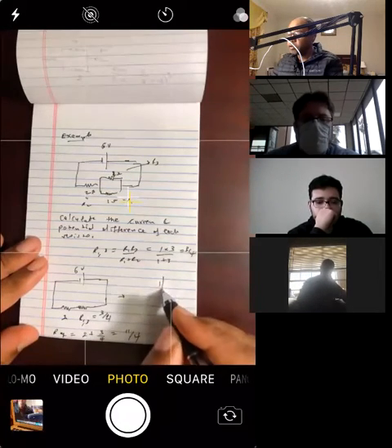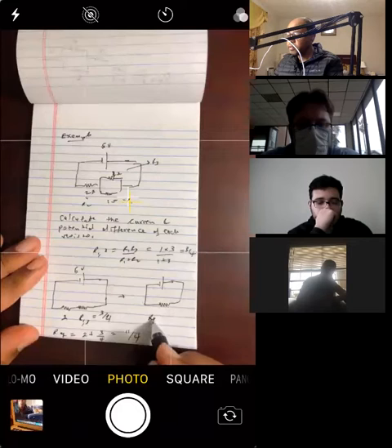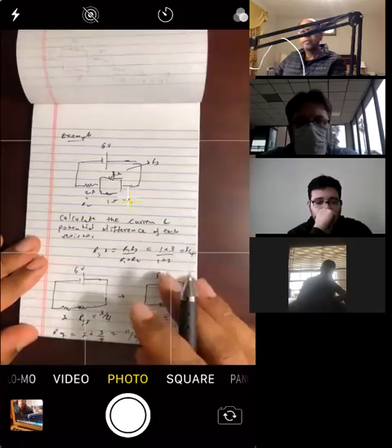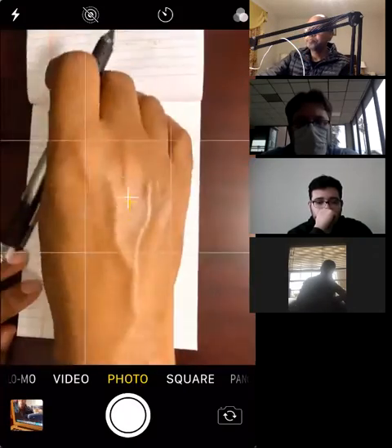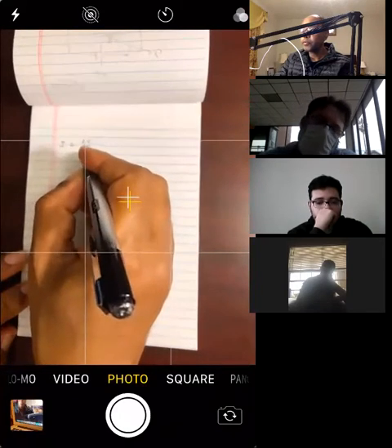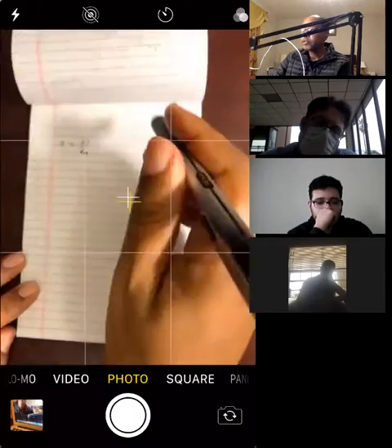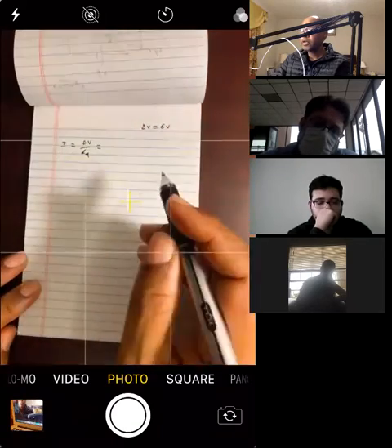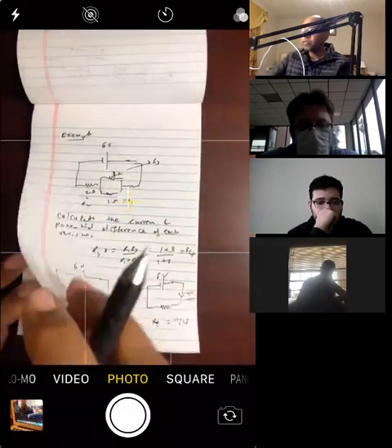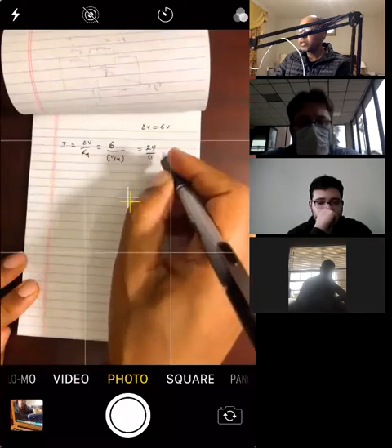So this simplifies to the following circuit. So you have a single resistor, which is the R equivalent, 11 over 4. Okay, you got 6 volts over here. Now we can calculate the current, right? Let's calculate the total current. So the total current is total potential difference divided by Req, right? The total potential difference is this one, 6 volts, right? So delta V is 6 volt, and Req we just calculated. So it's going to be 6 divided by the equivalent resistance, which is 11 over 4. Okay, so divided by 11 over 4, and that is 24 over 11 amps.